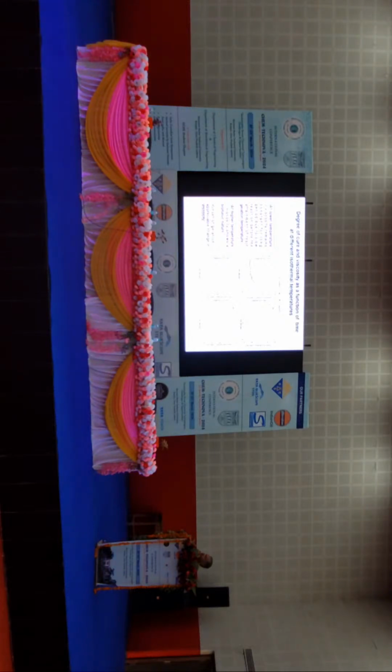Next one, please. So whatever rheological data I have obtained, with respect to the superimposed data, viscosity as a function of degree of cure and temperature, has simply been fitted to certain equations. This model is only applicable when the degree of cure is less than the degree of gelation, that is, only for the viscosity variation up to resin gelation.